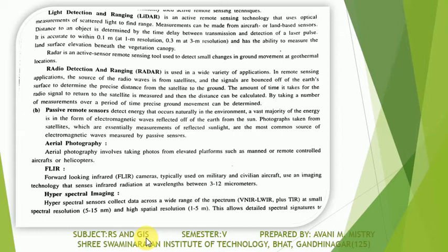infrared cameras, typically used on military and civilian aircraft, use an imaging technology that senses infrared radiation at wavelengths between 3 to 12 micrometers. Hyperspectral imaging. Hyperspectral sensors collect data across a wide range of the spectrum. Okay, VNIR, LWIR plus SWIR, with small spectral resolution and high spatial resolution of 1 to 5 meters.